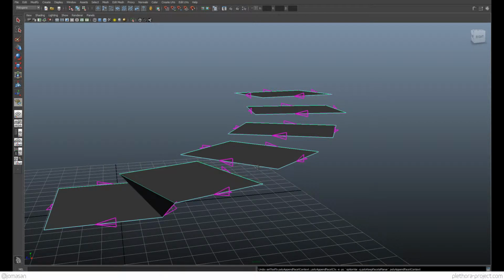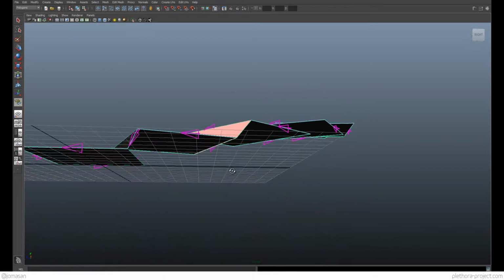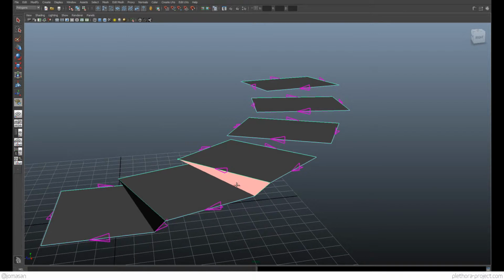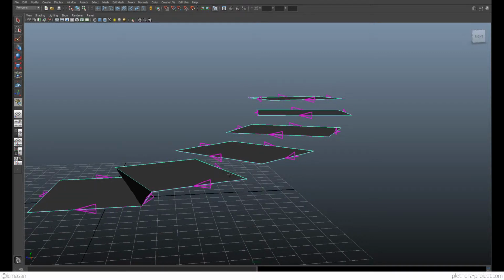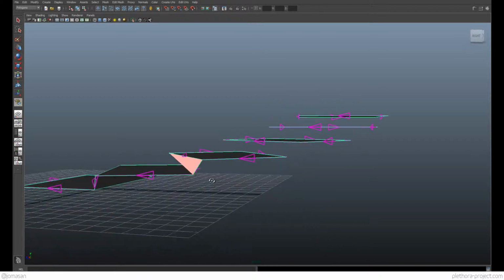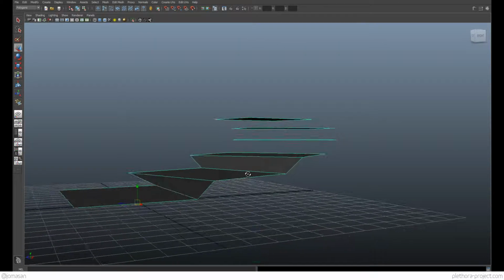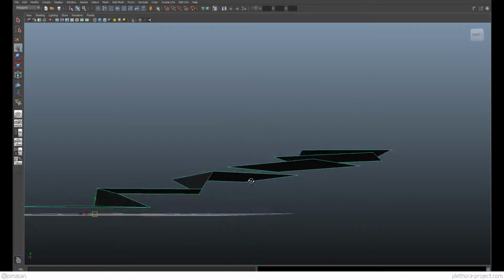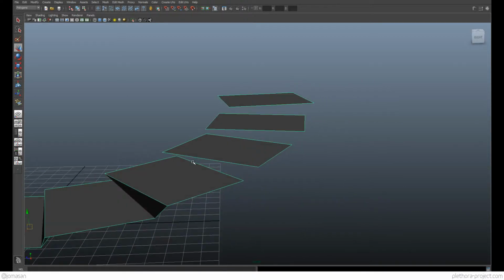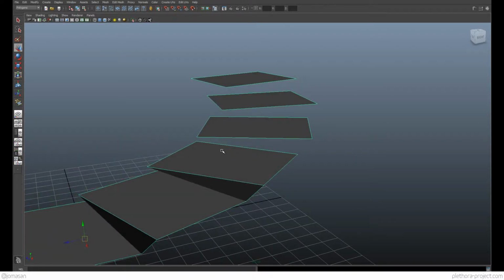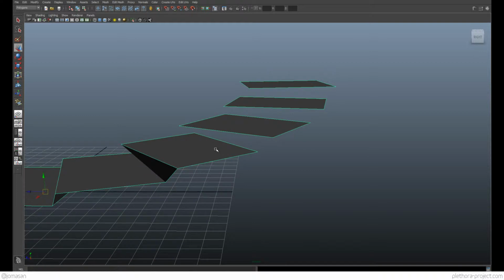See that I kind of made a mistake there. There we go. If you click somewhere else, you can always press delete to go back one step, and you see that I have already selected this edge, and I get to select this other edge again, and that's fine, right? So that's a neat way of just starting to connect geometry. Let's see another one, which is the bridge tool, right?